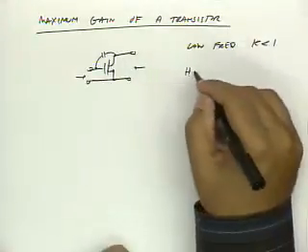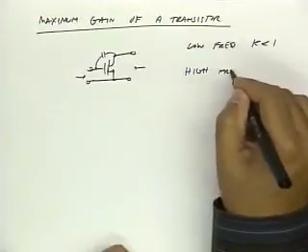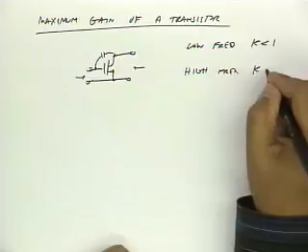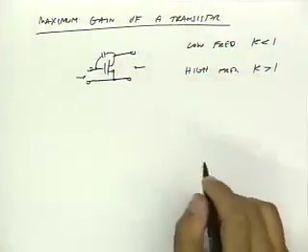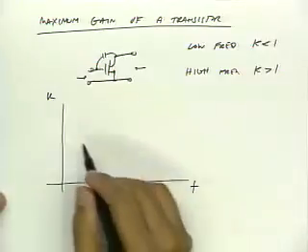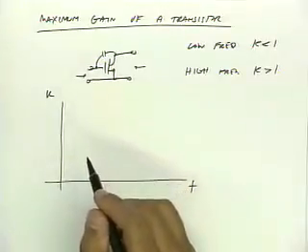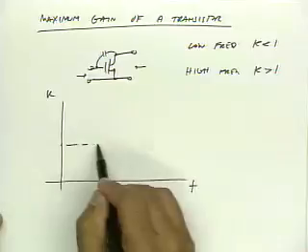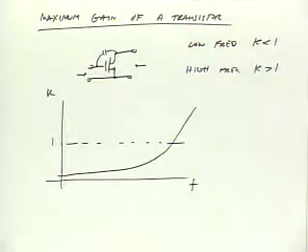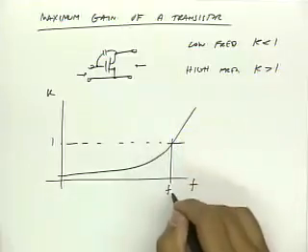At high frequencies though, what we call the knee frequency, there K tends to be bigger than 1. So if I were to plot the K factor versus frequency, it might look like, let's say this is 1. It might do something like that. Let's call this the knee frequency.